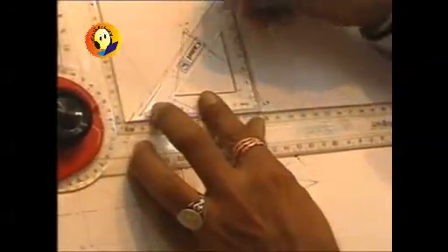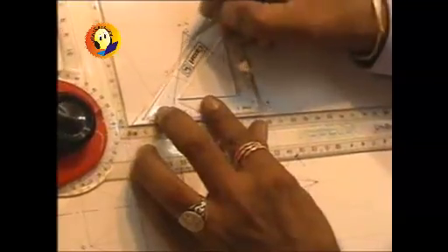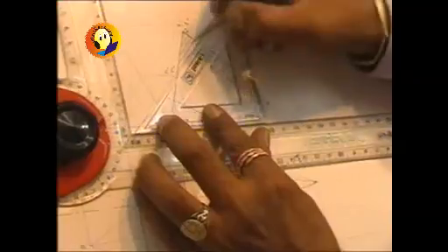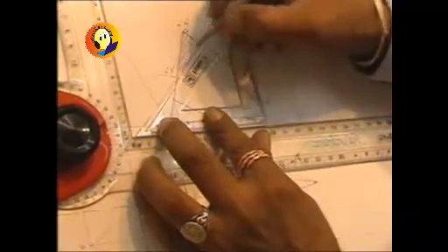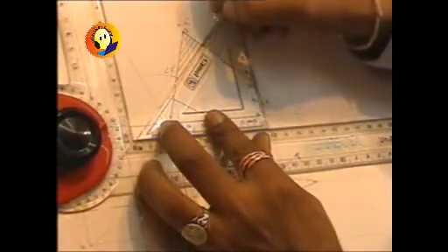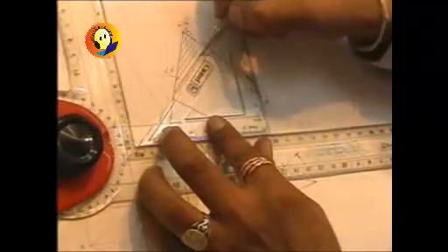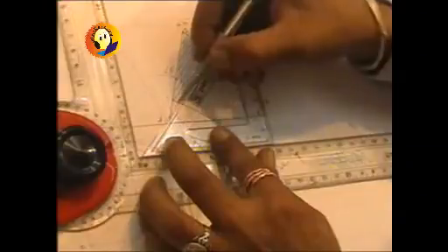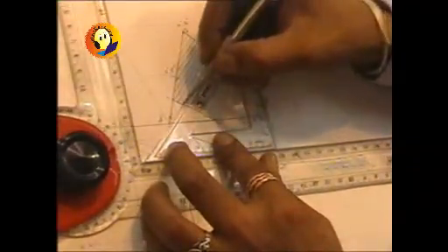And now it should be sectioned. Hatching lines should be shown onto it, which should be equispaced and making 45 degrees to indicate the section. Remember, this section is cutting the generators, it is cutting the base also. So its development is going to be the one which is very interesting.